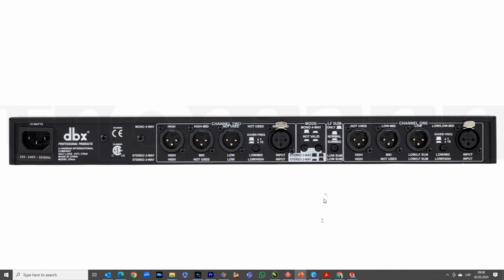And this is the best way to tune your system, because then all those room reflections are also included in your settings. I think it's a big advantage of active systems, because previously, when your crossover was fixed, you did crossover tuning based on measurements in an anechoic chamber, but when you put it in a room, you get different results in different places.